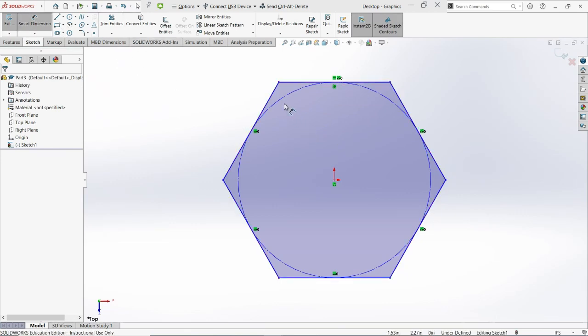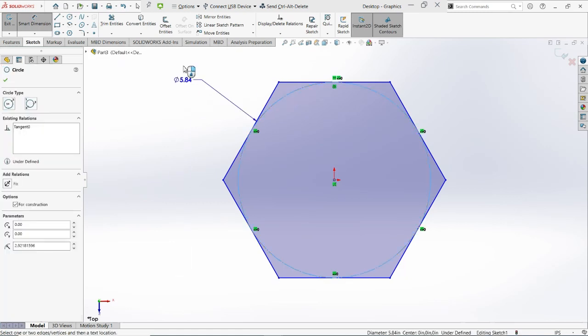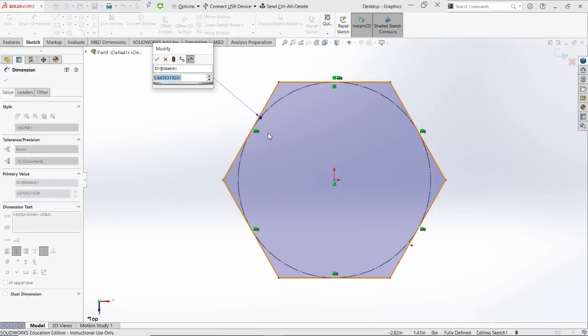If you wanted to add that here, you could extrude everything but that section. But in this case, I'm going to show you a different feature. Before we leave the sketch, let's dimension this hexagon itself, because having a 6-inch wide nut might not be as helpful as we'd like. Let's say we're making a nut for a 1/4 bolt.